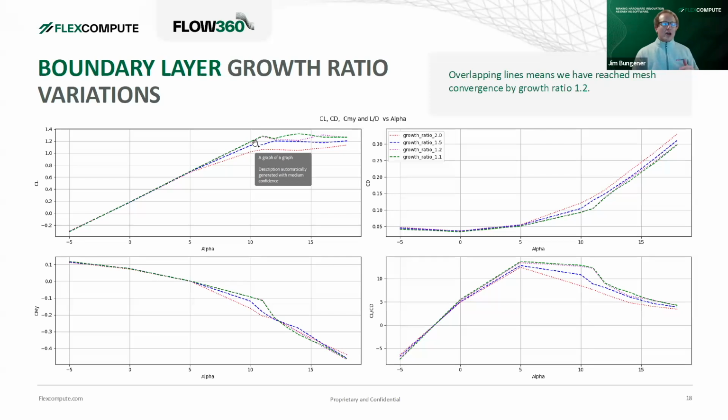So the idea is you keep on refining the mesh until the answer stops changing to within the bounds that you have set yourself before you started this mesh sensitivity study. And then the idea there is to get confident that, okay, this mesh is capturing the physics. I don't need to go to the very fine mesh. I can stay at the one before.